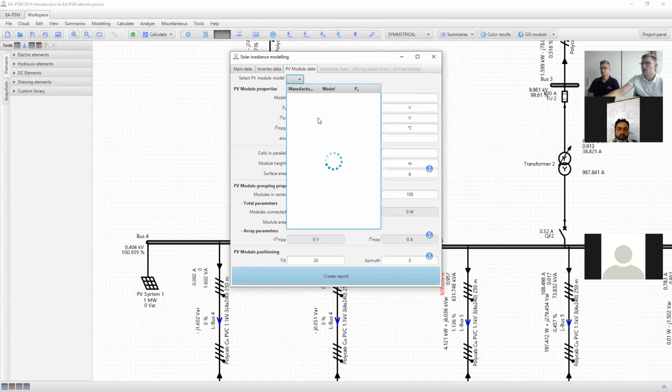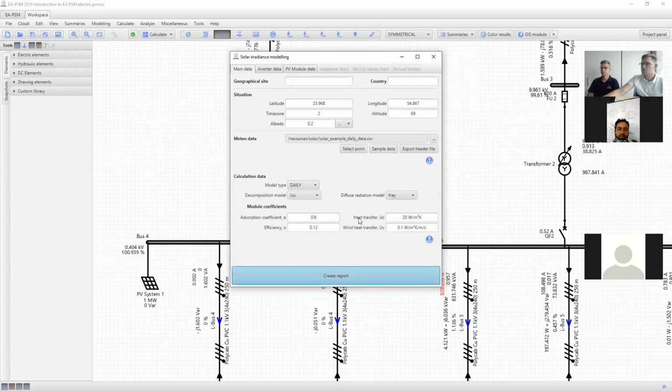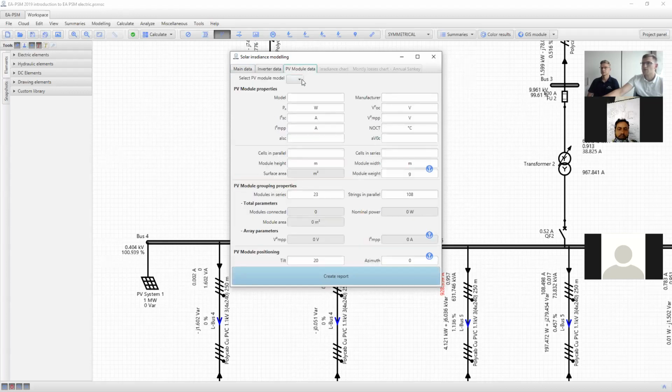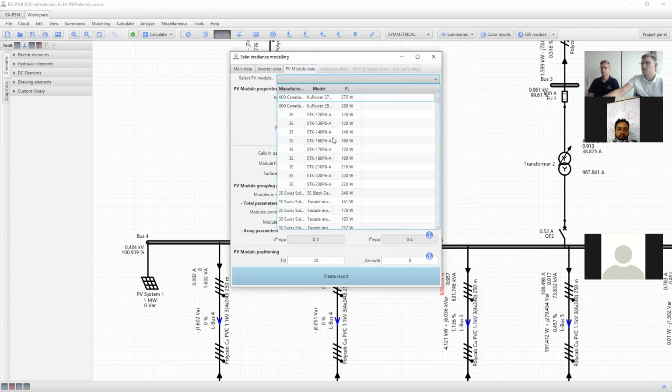And it is possible to select an inverter from various inverters, and select a PV module. So we have a broad library. Maybe in this version the library is not included, so technically you can specify it by hand. Then it is also possible to specify the tilt angle and azimuth angle of the solar power plant. This information should allow you to calculate irradiance on an hourly, daily, or yearly basis. Of course we need the PV modules to be loaded. Okay, I can see that these are already loaded.